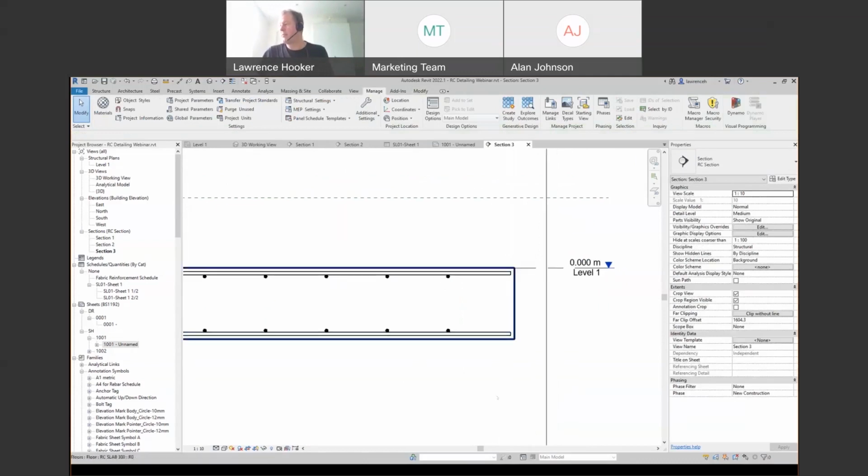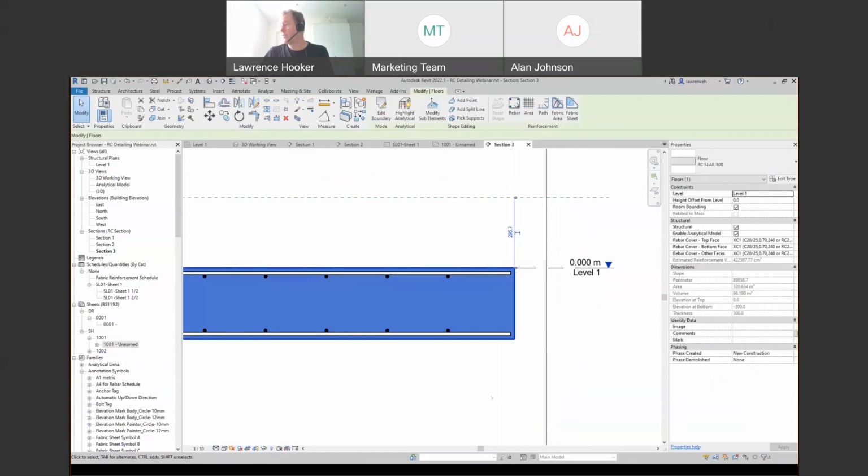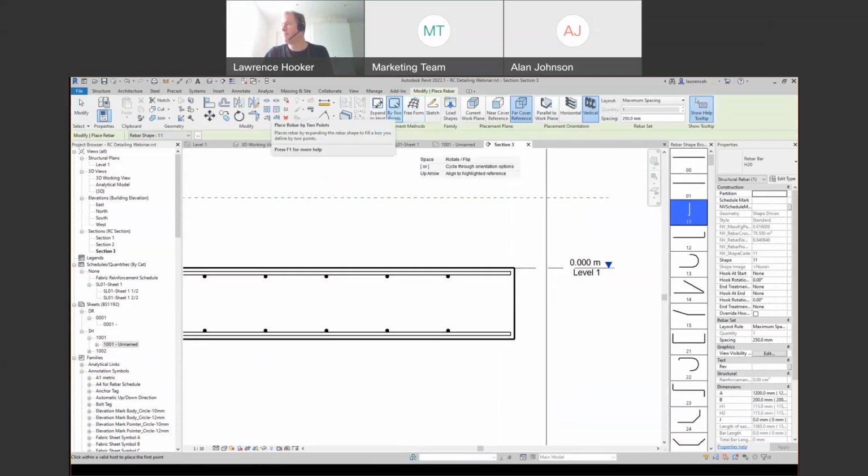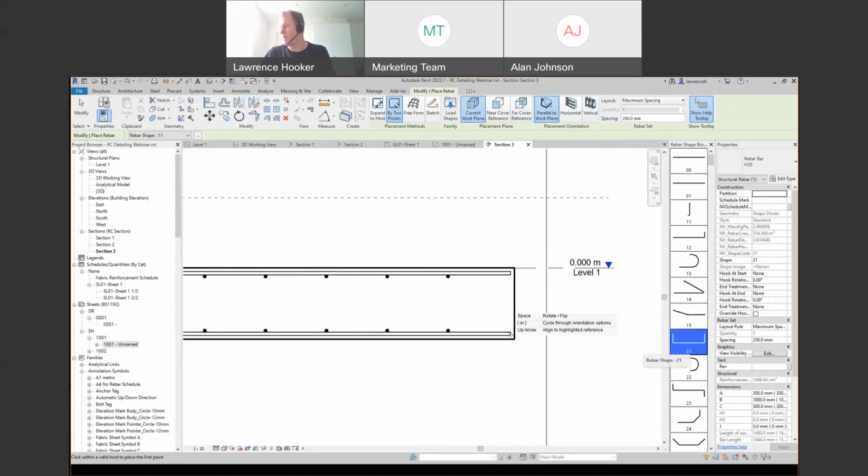And now what we want to do is sketch in a U-bar. And again, I'm going to use some new tools in Revit for this. I'll go to Rebar up over here. This time, I'm going to sketch by 2 points in here. I want this to be parallel to the work plane I'm currently working in and also on the current plane itself. And of course, I'm looking to sketch a shape code 21. And then we can just sketch this in.